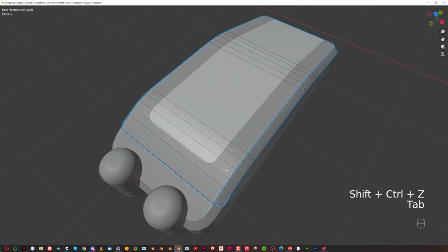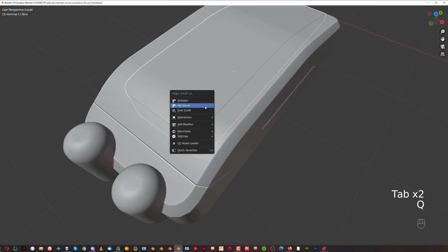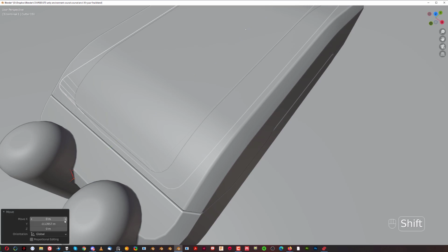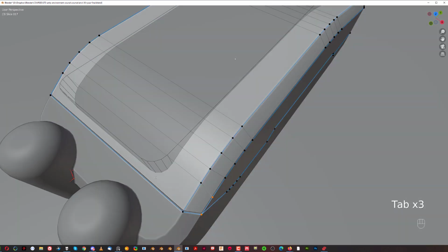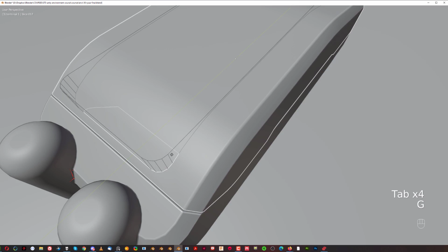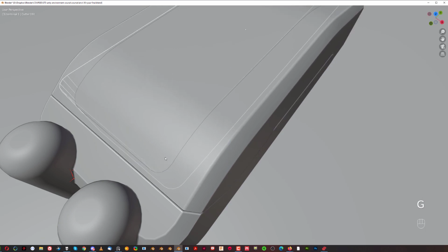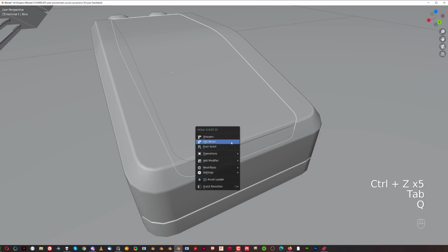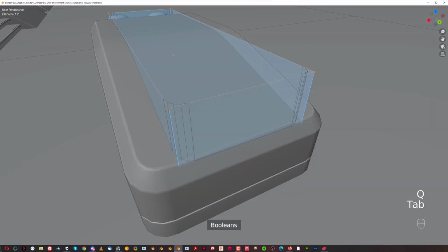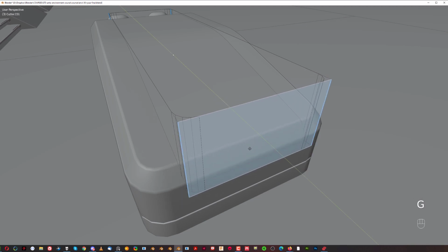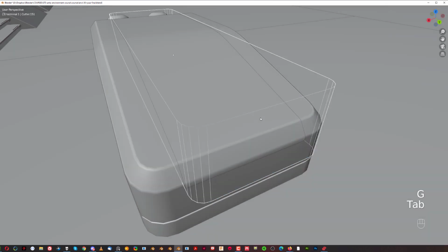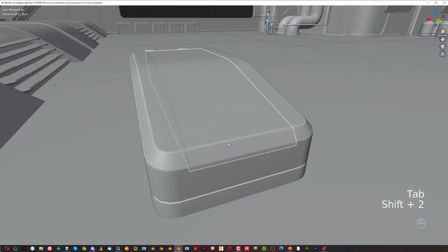Now before we apply this, you see they're gonna have some problems here, so let's move this either here or here. Either will work. You need to move it outside of the zone of the bevel, right? So here maybe it would work as well, something like this. So this side here is a bit unfortunate, so what we can do is grab this cutter and grab this one in GY and move it out here like this, okay? Even more like that. Alright, this is gonna be a bit better.